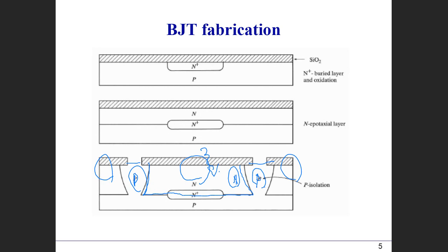Now for another device next to it, when you apply a certain bias, that also needs to go to the N P, this kind of configuration. So whatever bias you apply between these two BJTs, one of the junctions, NP or PN, always turns out to be reverse biased, which effectively blocks the current flow through the device. So that way you can isolate the individual device from the neighboring device by using these P layers here.